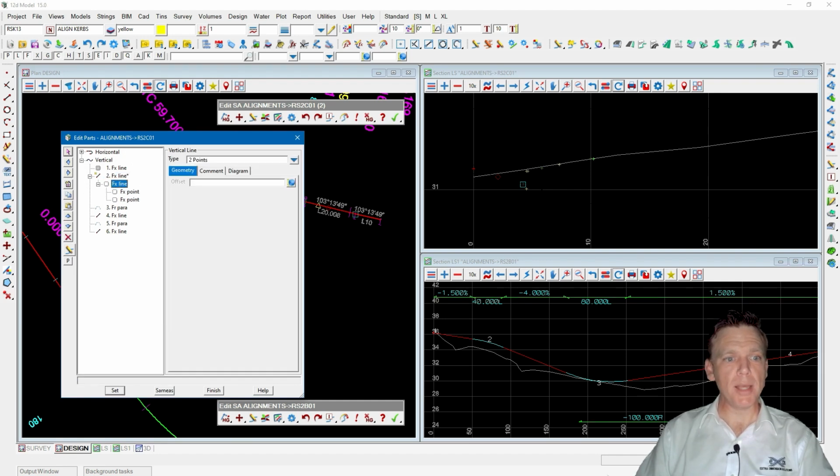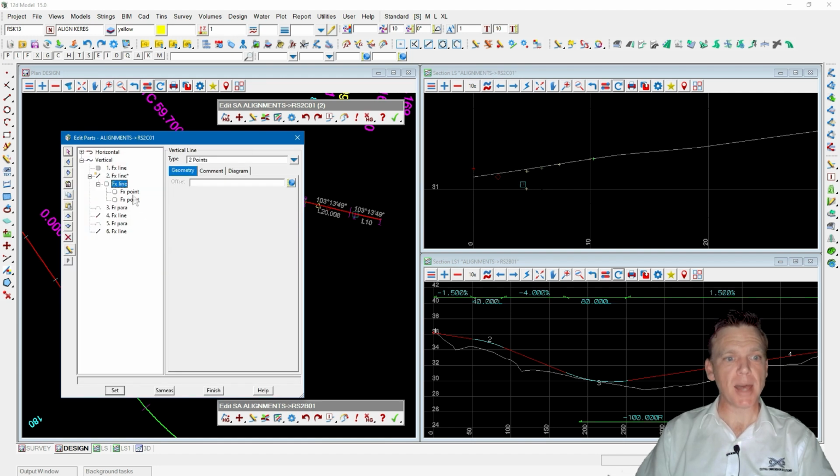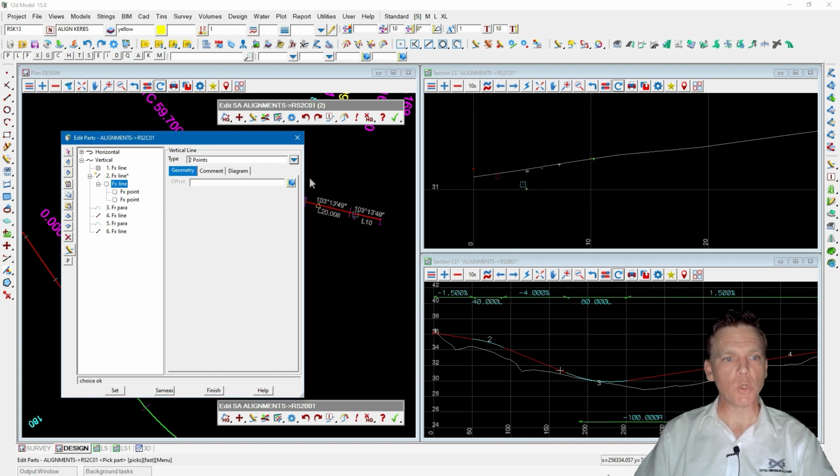We go 2 points, which is exactly what we had before when we had the chainage and height. Now essentially 12D is going to be asking me, okay, what are those 2 points and how do we want to fix those on together? Or we might just have the center line itself and actually nominate the grade, which was fine, again, if the geometry is at right angles and you know exactly what the grade is that you want to be projecting out at. But if you don't know, we're going to build it off the 2 strings or our 2 points.